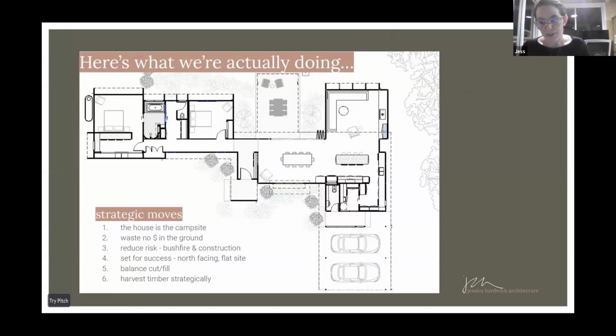That is the biggest thing you can do in the subtropics towards having an energy efficient and comfortable home. If you can face north and have some thermal mass that you protect in summer and that you really heavily expose in winter, you are doing really, really well. So we do go to length. Yeah, you basically eliminate the need for heating or even cooling, because you can utilize the passive solar principles.